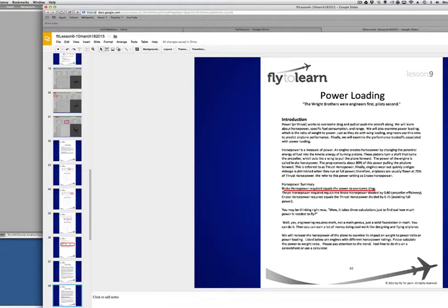If you think of it this way, say I needed 100 horsepower to get flying, but I'm going to lose 20% of it. Well, then I'm really not going to take off, huh? So if I figure out my propeller's 80% efficient, if I divide that 100 horsepower by 0.8, I realize what I really need is 125 horsepower, because I'm losing some of that horsepower to the inefficiency of the propeller. Side note, the Wright brothers' propeller was like 79% efficient.